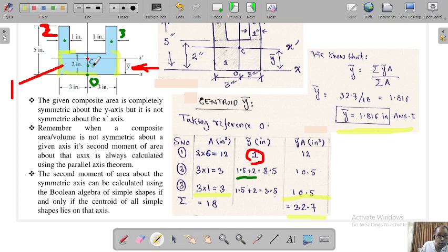If you look at it, you will be calculating the height along this and this, basically the distance between these two lines. Okay, so 1.816 minus 1. What this d is, basically, is the perpendicular distance between the Ix dash axis and the I1 axis, about the centroid of the rectangle. If you look at it, this axis and this axis, the perpendicular distance between them.